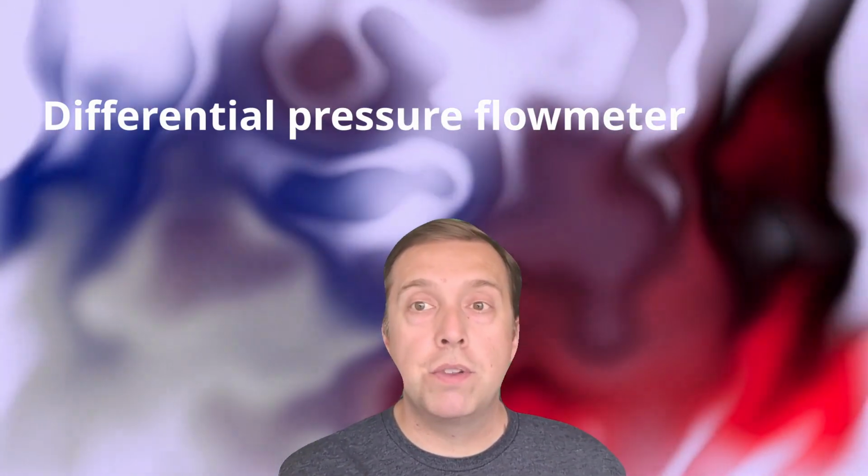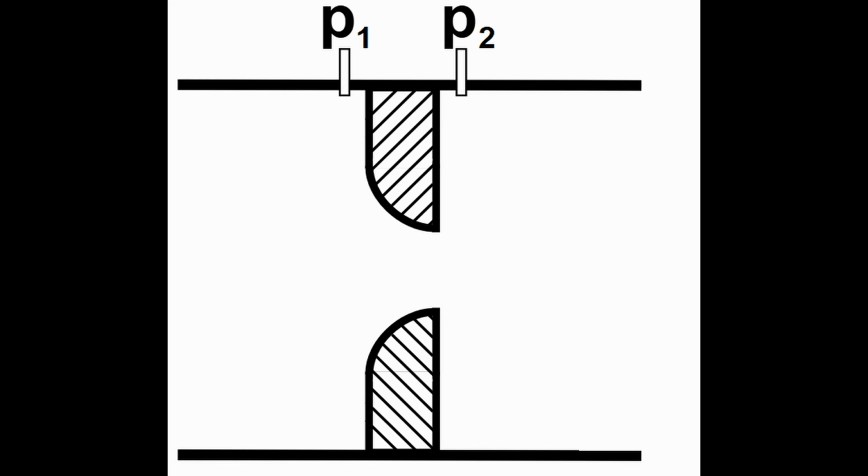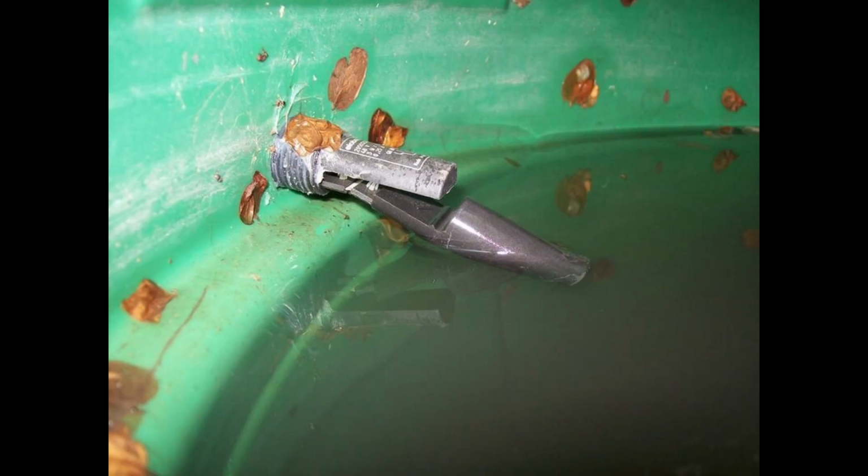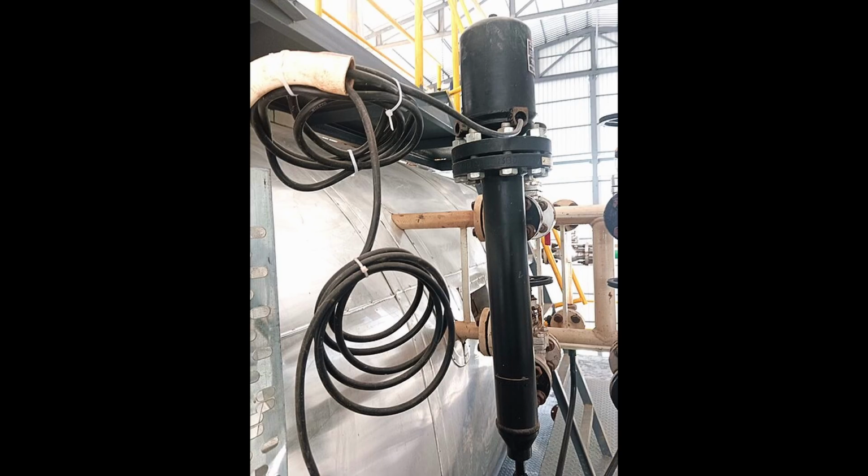We can measure the flow of a fluid using a differential pressure flow meter. In this situation, fluid is made to pass through a narrow opening. In doing so, the pressure in front of the opening is higher than the pressure beyond the opening. This pressure difference can be measured, and the fluid flow is proportional to the square root of the value. Finally, a water level sensor can be created using a simple float that is attached to a potentiometer. If the water level changes, the float will turn or adjust a potentiometer to change its internal resistance, which can be read by a circuit.